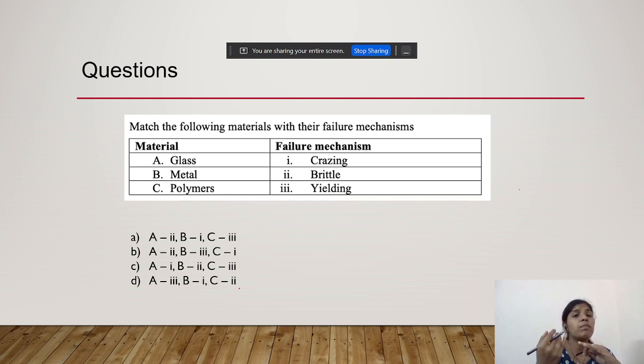Glass, metal, and polymers. These are the materials they have mentioned, and what is the failure mechanism? As we just now mentioned, glass is a brittle material, right? So the failure mechanism in glass will be brittle failure. And for metals, we already studied the failure mechanisms in steel, which is nothing but a metal, and it is a ductile material. So there you can see yielding in metals. In polymers, this is...